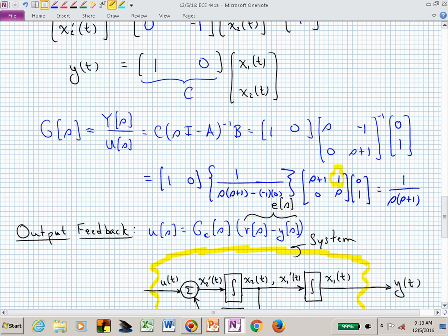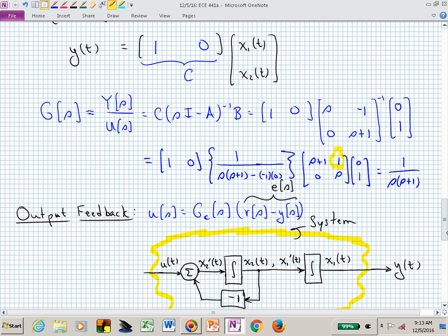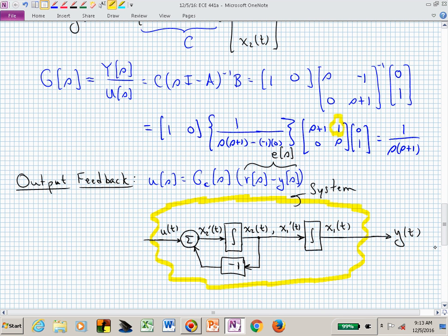And that's now our transfer function, and you should be able to see that transfer function as far as what it is doing relative to a complex s-plane. And if you just had pure output feedback, unity output feedback, you could see the root locus of that system. Where are your poles for G of s?